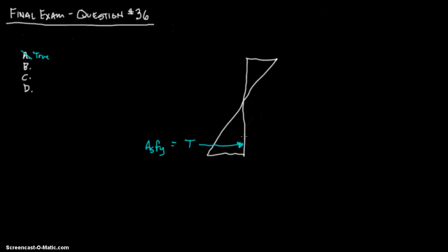So that is going to form a force couple, and you really don't want to think about it being this compression wedge down here, because that's not how it is. Instead of looking at this wedge, you actually get this compression block of depth a. Instead of doing the wedge, this is what is assumed for design. And this is a right here.